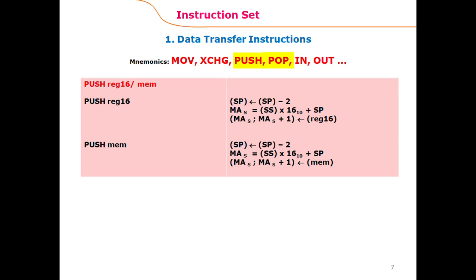Among the data transfer instructions, the main focus of this lecture is on the push and pop instructions and the in and out instructions. Of course there are other data transfer instructions, but this lecture is restricted to only these four: push, pop, in and out. The push instruction uses the stack segment of the memory to store data onto the top of the stack.